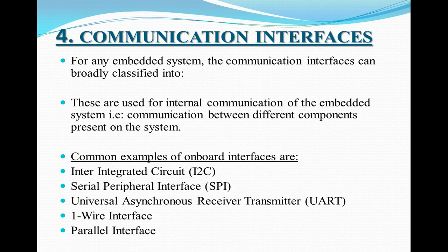Port pin means which port pin? Any port pin of the microprocessor or microcontroller you are going to use. Understood? So once the cathode is connected to the port pin, the LED is going to turn on and the port pin is going to go to 0, that is logic 0. So when the LED is turned on, the port pin is at logic 0. If it is not connected to the port, it is going to be logic 1, that is high.